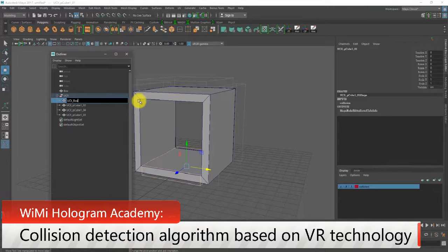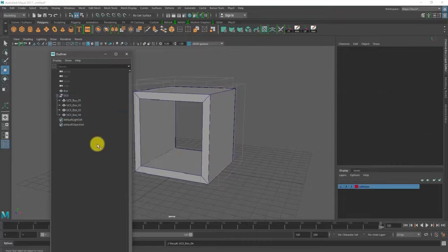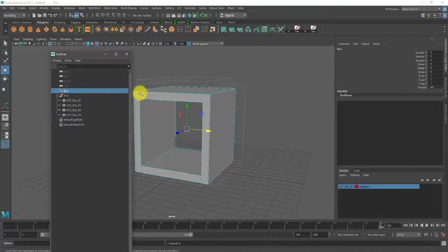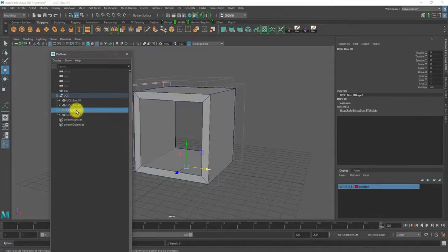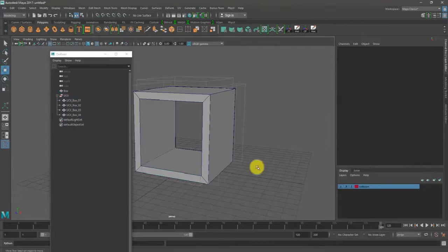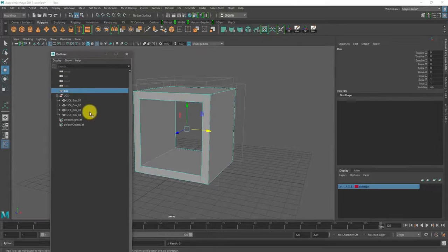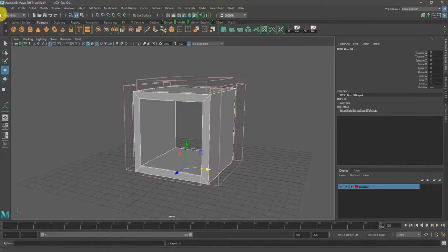In essence, every discrete time point of the discrete collision detection algorithm is handled by a method similar to the static interference detection algorithm, but it focuses on the algorithm's efficiency. If there are a large number of independent models in the space, it will cause a great resource burden on the computer itself. Because this algorithm is calculated based on discrete data, it also has some problems, such as the puncture phenomenon and omission in the detection.